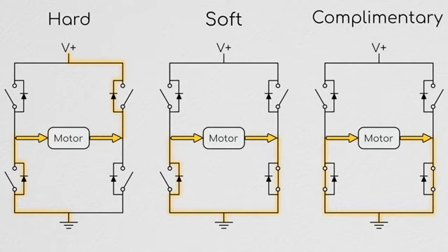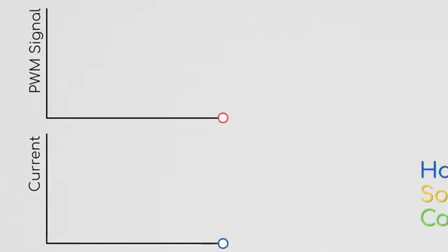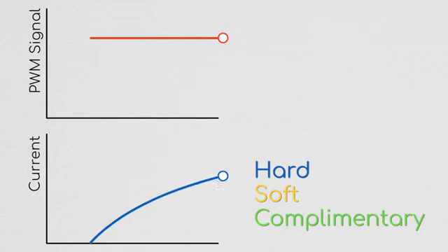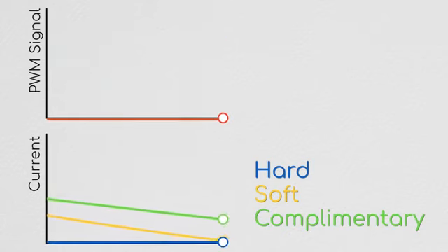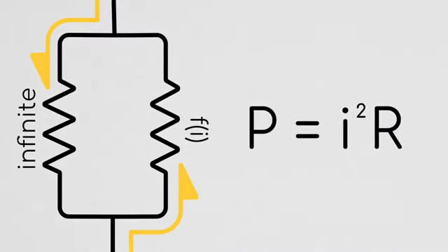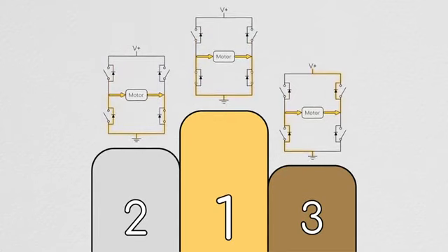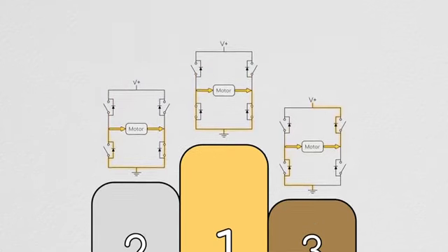During hard switching, this will be over 2 volts, not to mention the fact that it'll be flowing against your supply voltage. This voltage pushing back on the current will cause it to decay more quickly, and this faster rate of decay makes high-resolution current tracking more difficult. Additionally, the resistive energy losses in the diodes during hard and soft switching mean that your overall efficiency is lower. For all of these reasons, it is generally recommended that complementary switching be used during 6-block commutation.